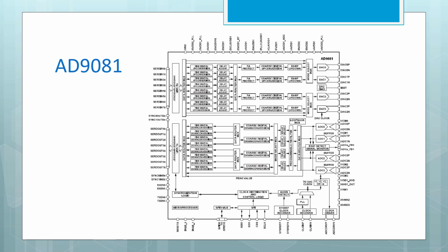So what we're going to be focusing on in this video is how to control those local oscillators, get them started in the same phase state, and then how do we see that? How do we confirm that that's the way that the chip is operating? This is an important issue if we're doing something like beamforming with the chip, because the local oscillators are setting the phase of each of our channels, and the phase is basically what we use to address beamforming issues.